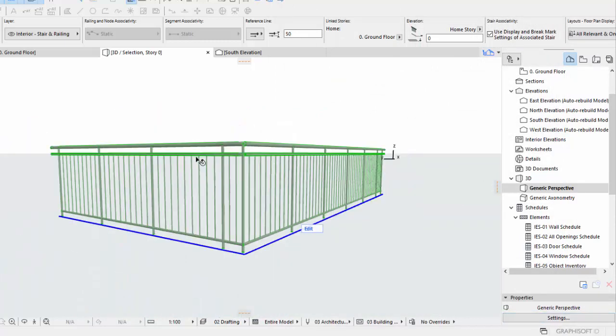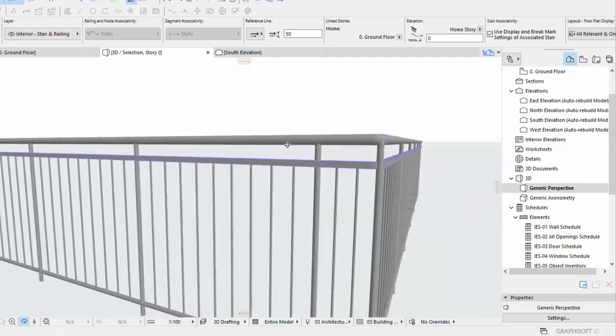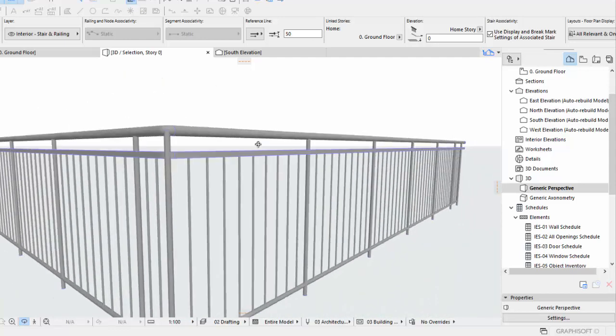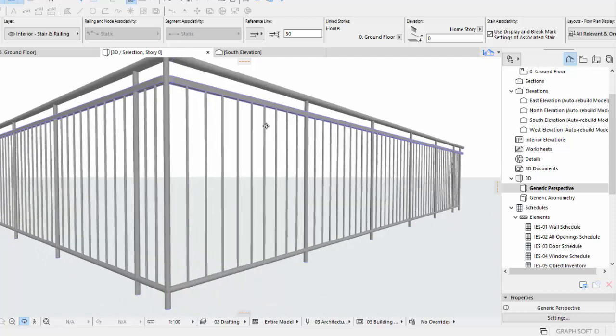Okay, so Archicad is quite flexible. So the thing is that normally this pattern of railing is not there. Unlike Archicad 19, which has this already and we just go ahead and draw easily like that. You've made it easy for us. But this Archicad makes this flexible. You can use a particular pattern of Archicad railing they gave to you and convert it to what you actually want. So that makes it really flexible and nice to work with, and it's easy to draw.